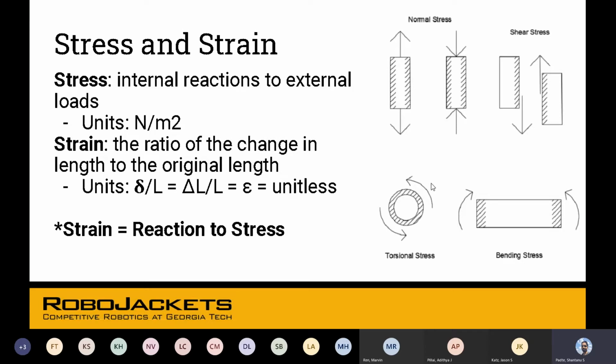Whereas shear stress is applied in a direction that is parallel to a surface, while normal stress is perpendicular to the surface. This is the surface and the force is being applied downwards. It's perpendicular. Shear stress is parallel. This is the surface and there is a force being applied here, generally due to friction.